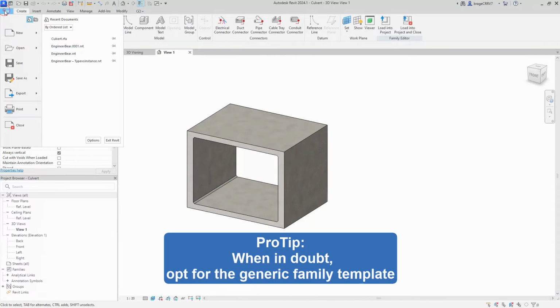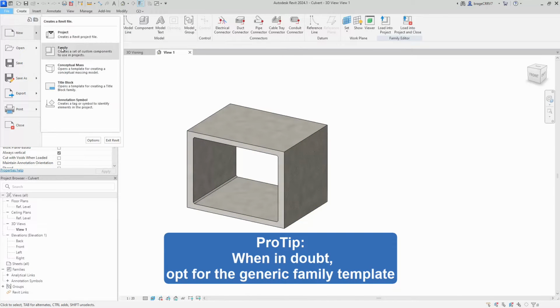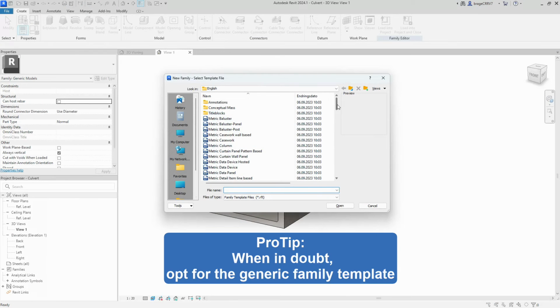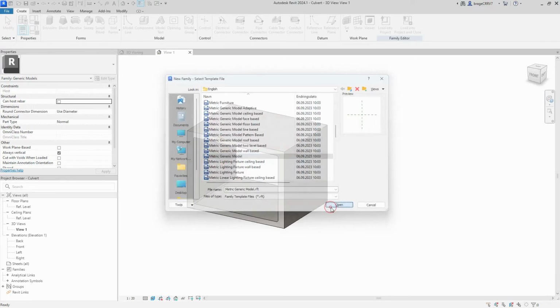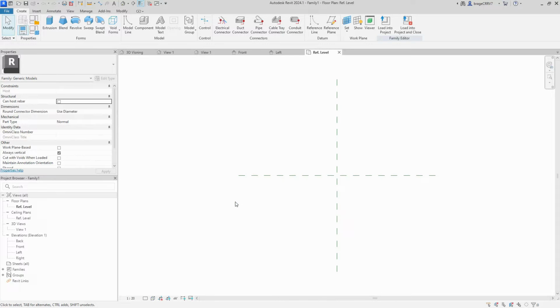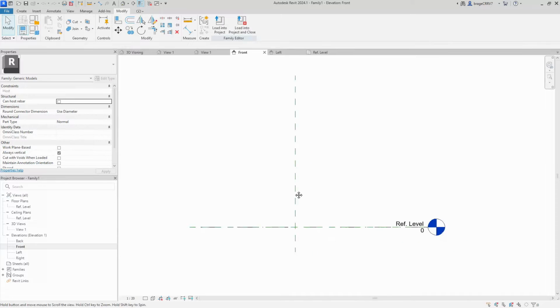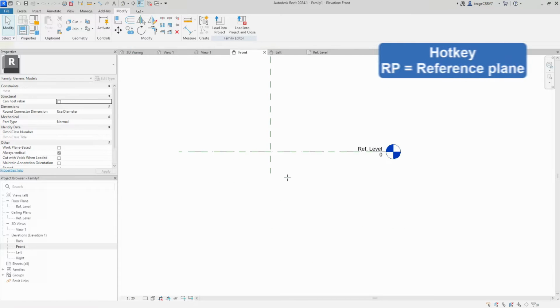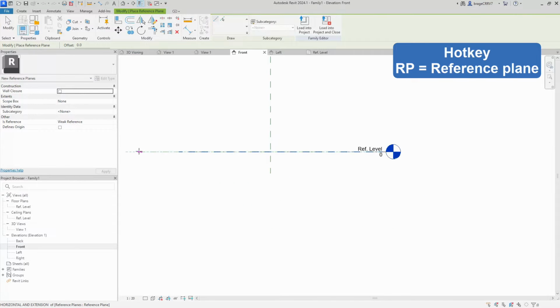There are several ways to go here, like a sweep with a 2D nested profile or a line template, but we will go for the generic. It is a safe option. This edge, as mentioned, will not be parametric, as the geometry remains constant, since the primary objective in this video is to create a yes-no parameter that grants us the ability to activate or deactivate these edges as well.